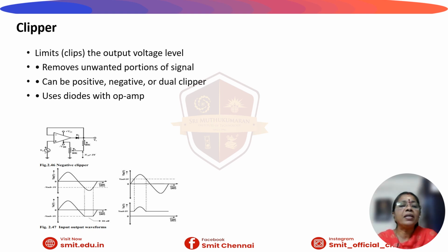Here the input signal is given to the non-inverting terminal and a feedback portion of the output voltage is connected back to the inverting terminal. Thus, it acts in voltage follower mode. The reference voltage is given to the positive supply. Thus, the circuit acts as the positive clipper.